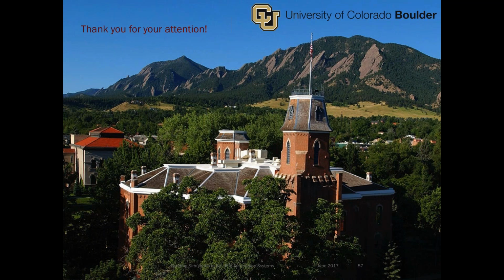In offline studies, we could implement the entire day because nothing really changes and we have perfect knowledge. But in real-time control, we forecast the next day. So we have the next day's weather, pricing, and building utilization information, and we implement just the first set point or the first control vector for the first hour, and do that in a receding fashion.